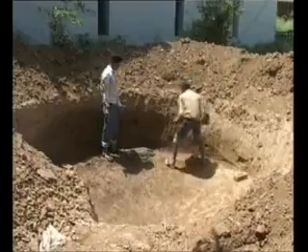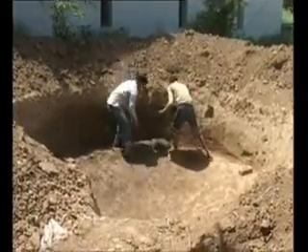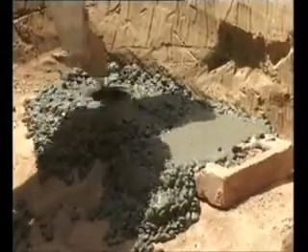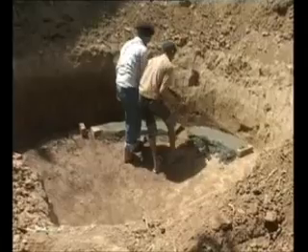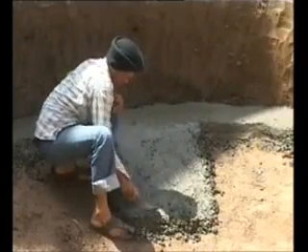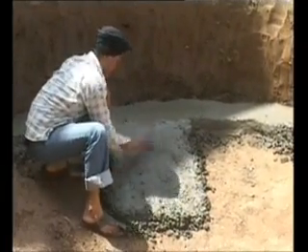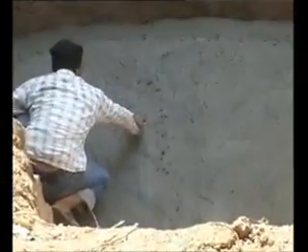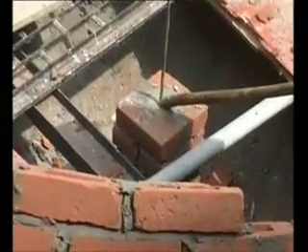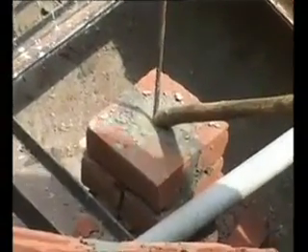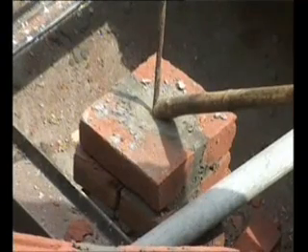The foundation of the digester is laid by putting a 3-inch thick concrete layer in the ratio of 1:2:4. While putting the concrete layer, we maintain the circular slope. After completion of the foundation, we start the construction of the upper part of the Deen Bandhu biogas plant. For the construction of the upper part of the plant, we fix a wooden stick at the center for measuring the actual radius of the digester.